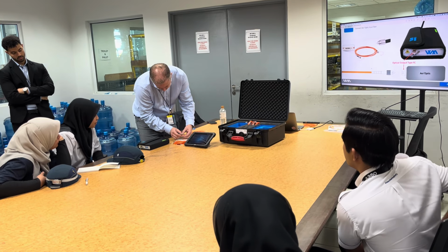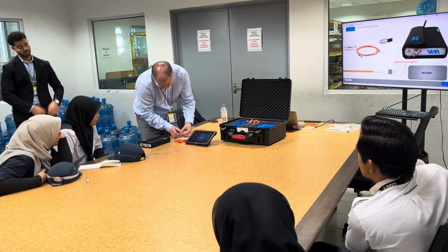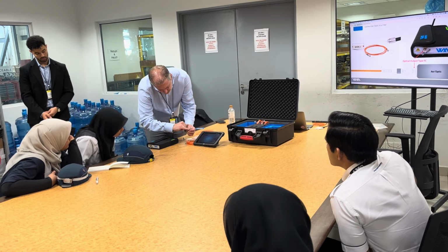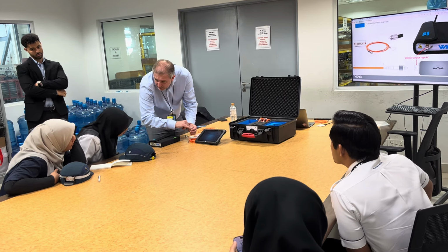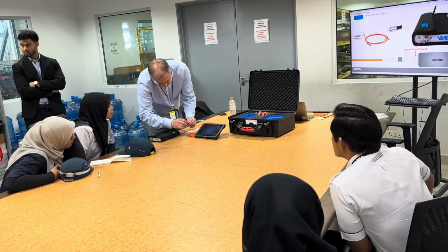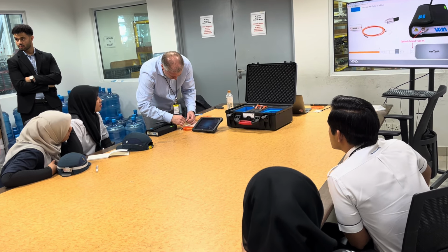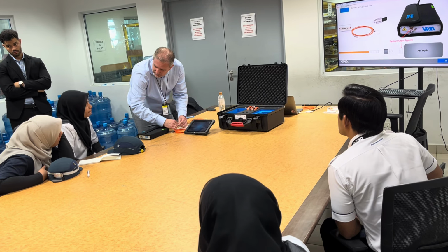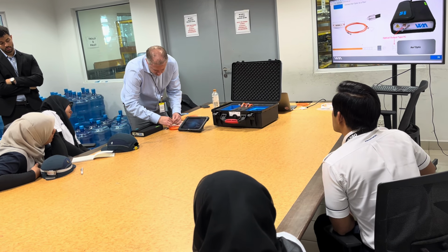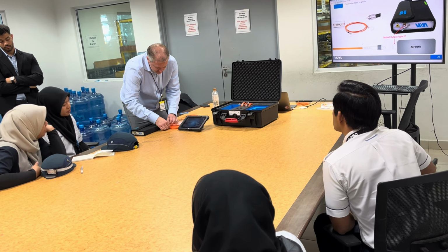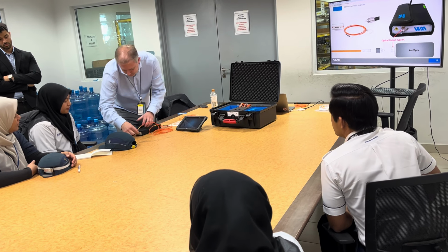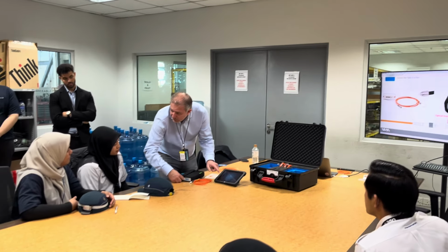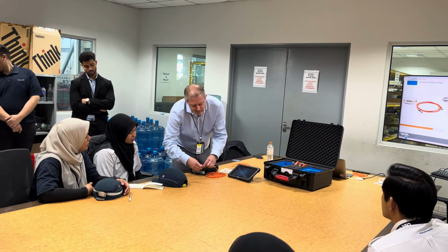So when you connect the FC connector, you have to be careful. There's a small part there. I don't know if you see it. Well, you will come and practice after. You have to make sure to align it, and then you feel the spring, and then you can screw the system. Then I can do the same over there. It's not emitting. As soon as I don't run a test, I have no emission, so I can safely connect to it.